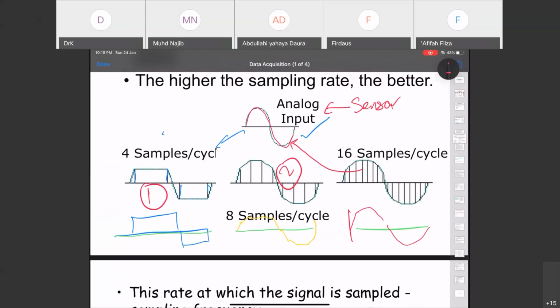But when you are working with your input signal, for example a power line signal where you want to collect power disturbances, or some of you may be working with biomedical signals, or noise signals, radio frequency and all that, how do you select the best sampling rate? If you select the wrong number, lower or higher, you have information loss. So what to do?